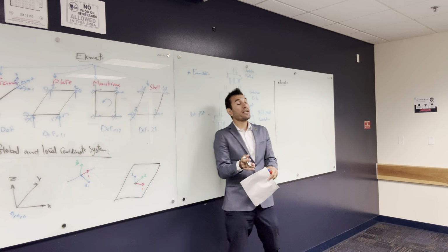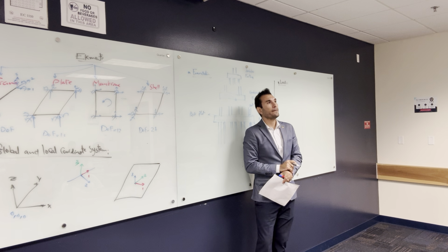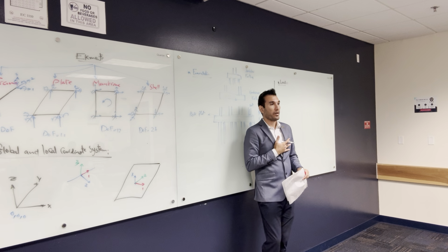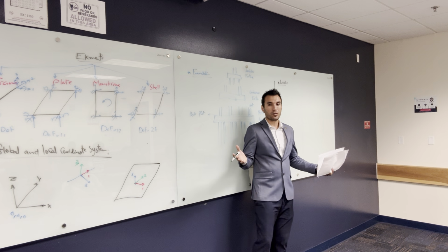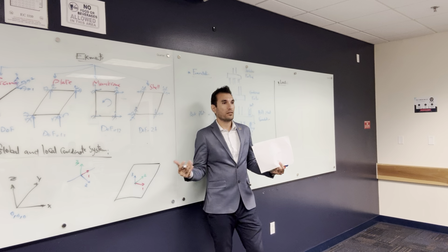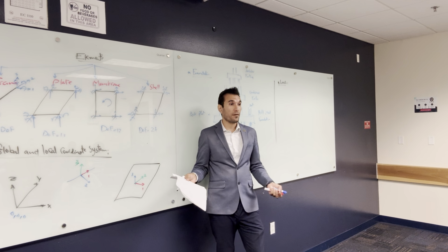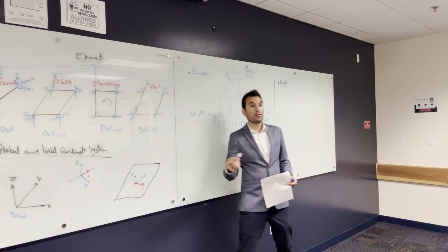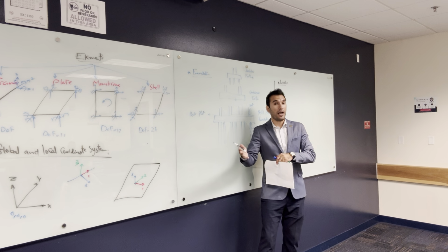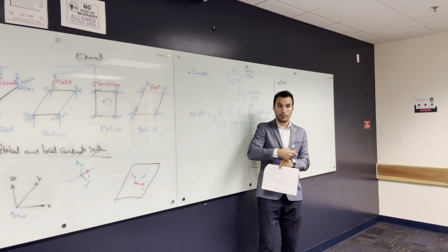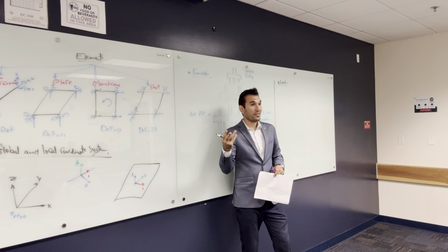Okay? And I make another dead load, it's called super dead load. This super dead load has the flooring, and I calculate the flooring by myself because every structure is different. Some structures are gonna have wood flooring, tile flooring, marble flooring. Everyone has different weight. So I make a load case, it's called super dead, and I calculate this load and I assign it inside this load case. Okay? So right now we know dead, super dead.